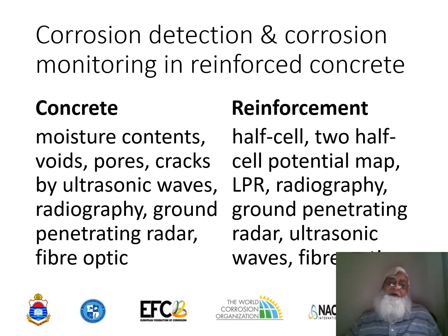It gives a relative corrosion rate, not an absolute one. It doesn't measure the corrosion of the actual steel but the corrosion of the probe, and the probe has the same material as the reinforcement, indirectly giving a corrosion rate of the steel reinforcement.